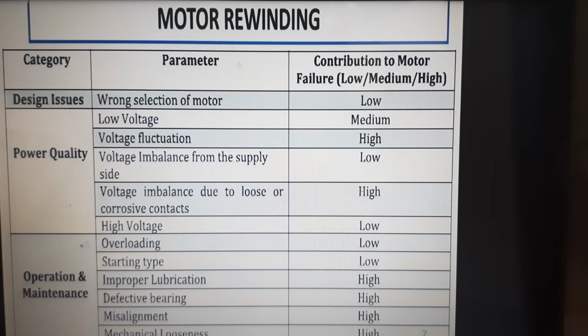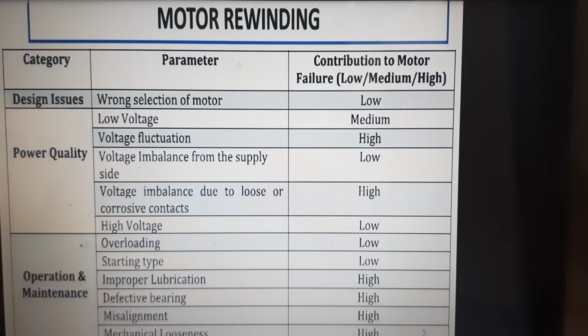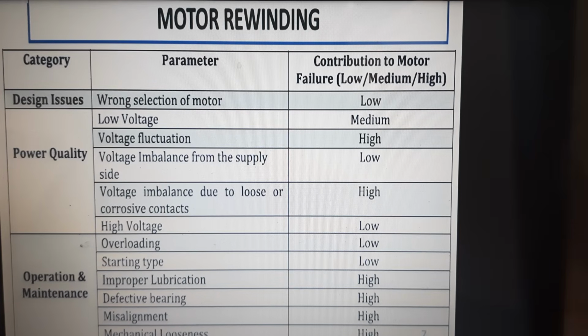On the maintenance side, a defective bearing means heat dissipation will not be there and the motor gets heated up more, and there is misalignment or mechanical looseness on the grouting of the motor. These are all high inputs with a higher contribution towards motor overstrain, and if not attended to, it goes to motor failure also.